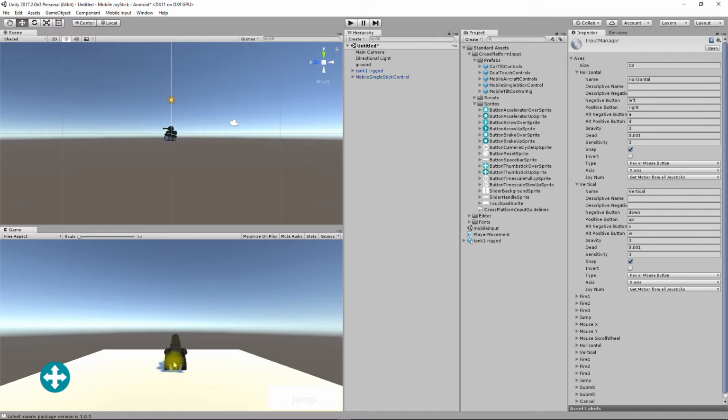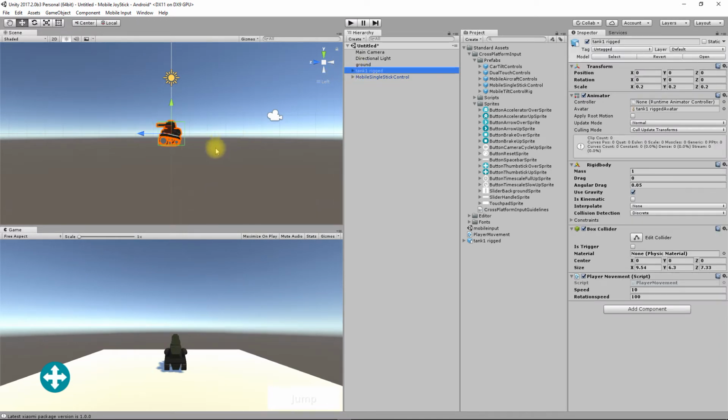And what we want to do with this object here, with our tank, is we want to turn the horizontal movement, so movement on X, into rotation of our tank, and then we want to take our up and down, or Y movement on the joystick, and turn it into movement on Z for the tank, because if we look at the tank, forward and back for the tank is Z. So X will be rotation, so movement left or right, which is on X in our 2D window, will be a rotational value, and that'll be rotating on Y, because Y is the up axis.